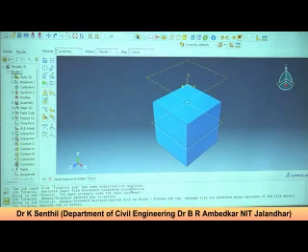The second thing, sometimes if your material properties are wrong, if you entered material properties like density, Young's modulus, or insufficient material properties, that causes this error. Another thing, sometimes the loading patterns, that's what the professor was saying.